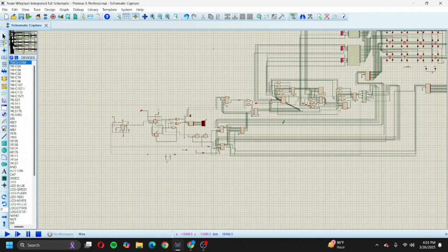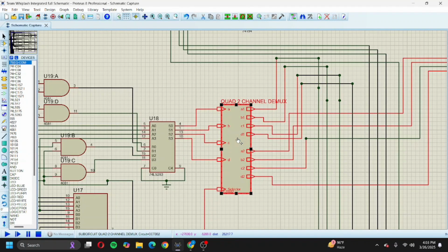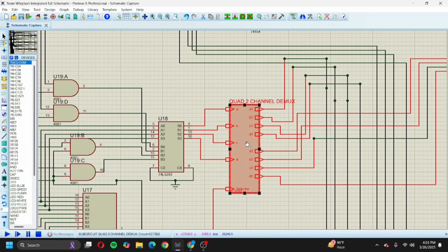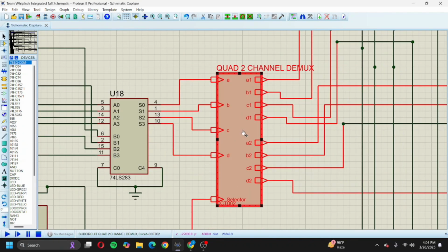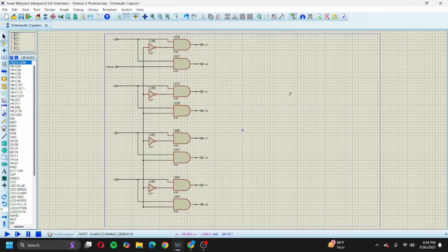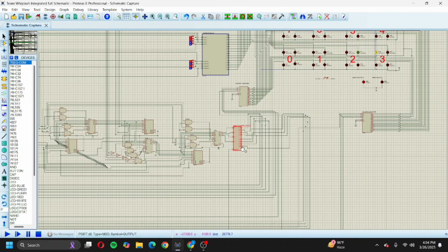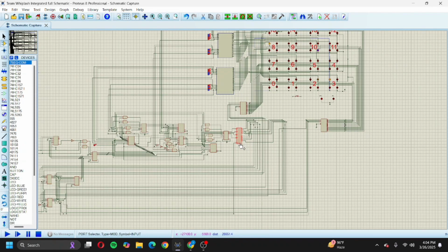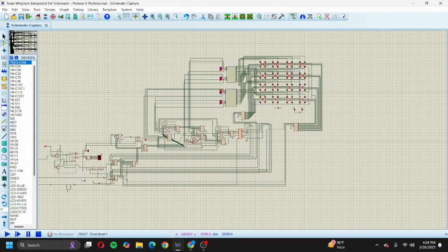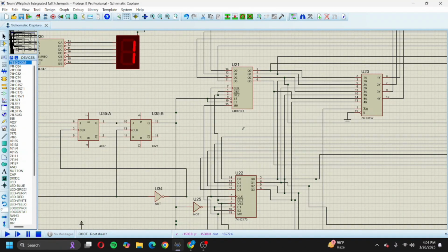And also, after passing through the logic module, we built a DMUX with a subcircuit because we didn't find any properly working IC for DMUX. And this is the child sheet of the DMUX. And the function of this DMUX is to pass through the updated value of the current player's position and make the registers take that input.